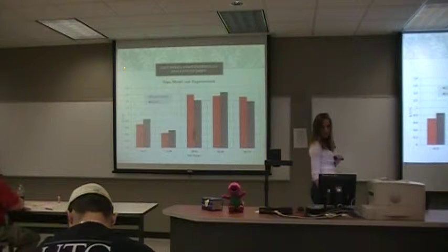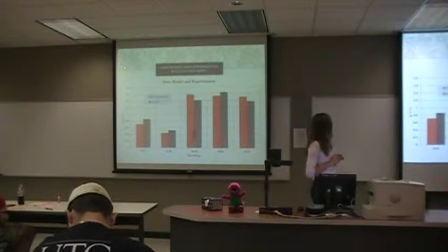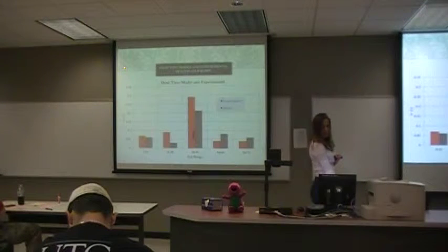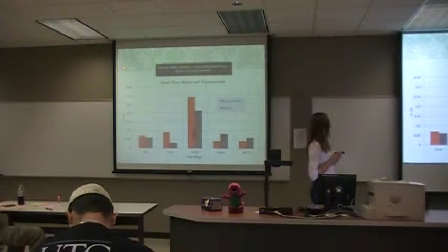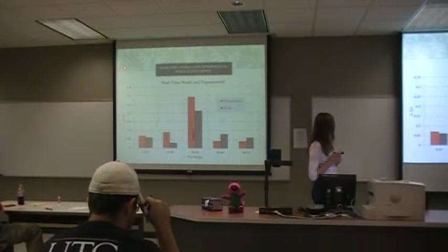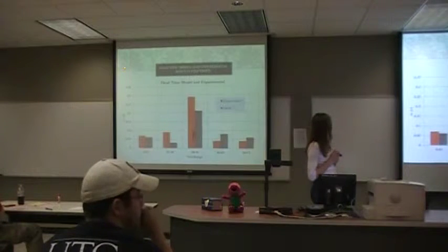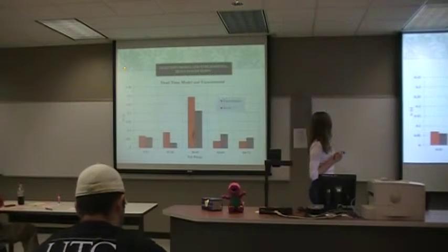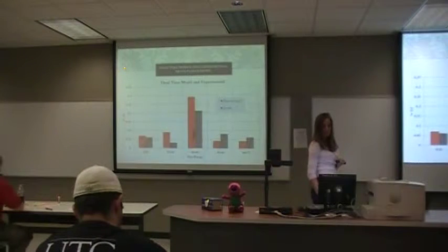And here is for the step down, same idea. We got low gain for the lower regions and then higher in the 30 to 75 volts. Dead time, 30 to 45 volt range was the one that didn't really follow the norm, but generally the other ones stayed about the same. And like I said, the difference really isn't as big as it looks because our dead time is so small.